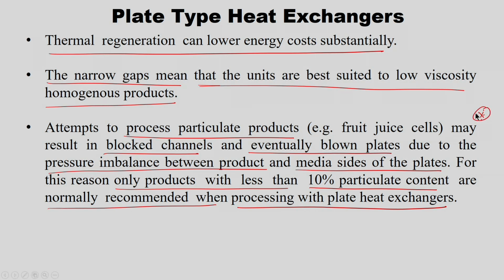So, we cannot process liquid food with more than 10% particulate content, and regeneration is possible in the plate type heat exchanger, which lowers the energy cost. And there are many variations of the plate type heat exchanger. So, how to take care of each and every plate and which type of grooves should be there, based on the product we can select them. So, in which way we want the plate type heat exchanger to be designed.